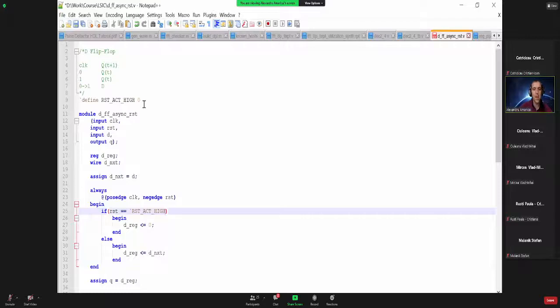So you do not act on clock and reset with conventional logic. You just have input clock, input reset, and you leave the design as it is. You use the posedge of the clock, you don't have clock equals to whatever. Good.